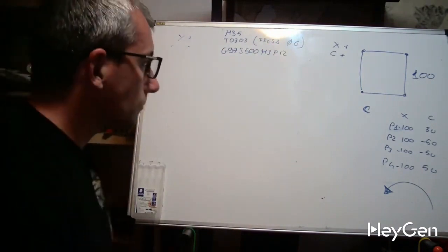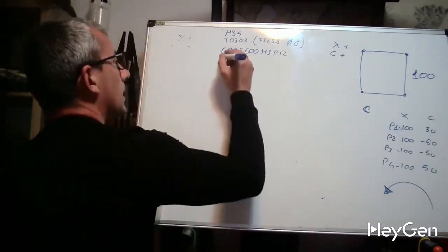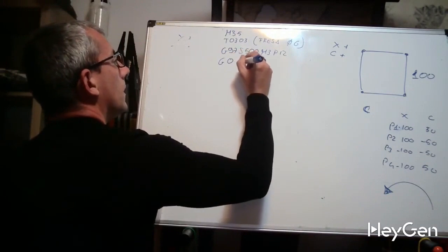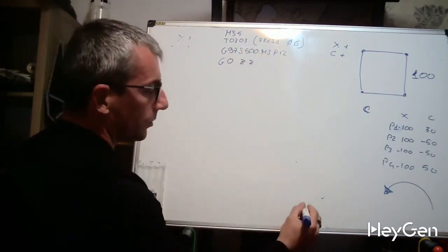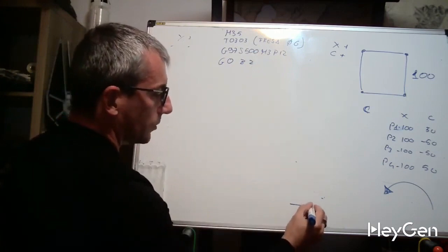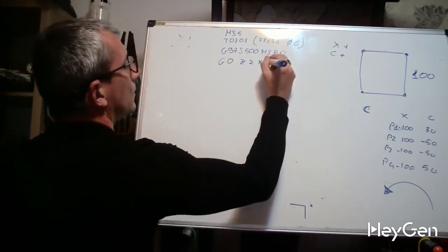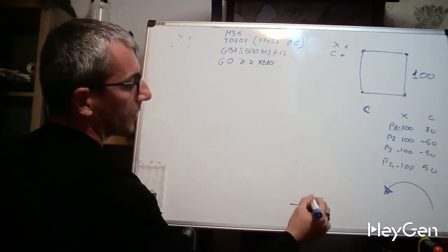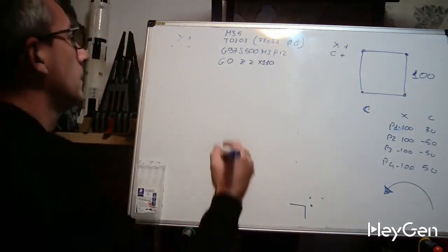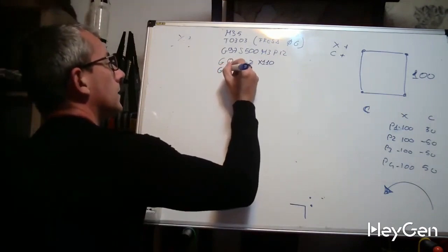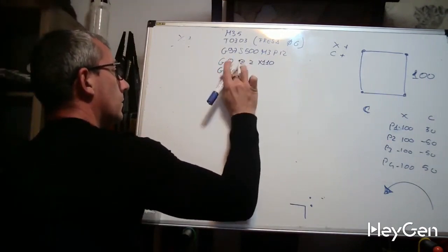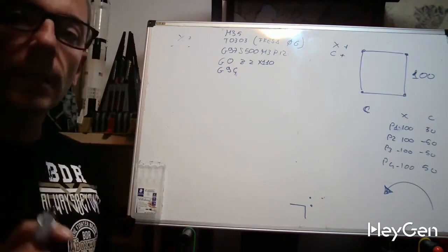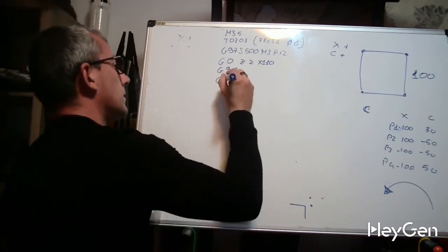Then we swiftly move to G0, Z2, because obviously we need to mill a square, so we move there. Here, X110. So, higher than the frame that we need to mill, we enter. If we want to work in millimeters per minute, the G94. And this is the moment to enter, in a separate block, without any other code, the G112.